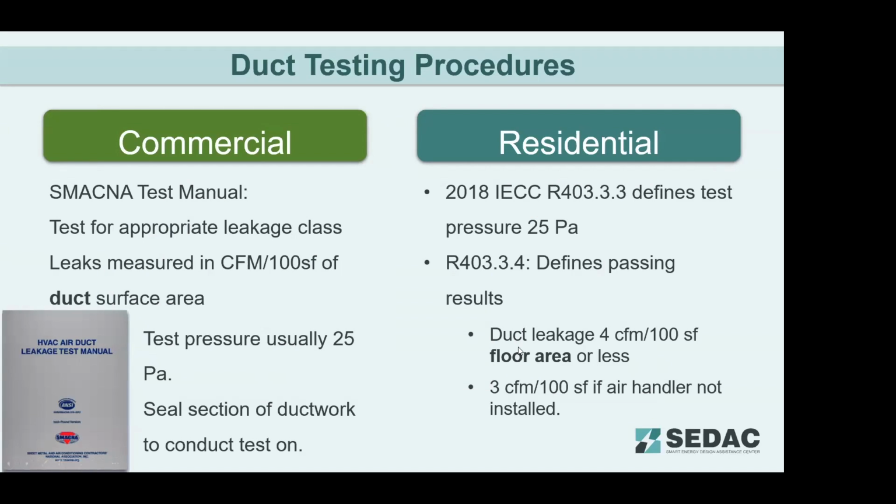So duct testing procedures, as Sean mentioned earlier, for commercial, reference the SMACNA test manual. Check your appropriate leakage class. Leaks are measured in CFM per 100 square foot of duct surface area, usually at 25 pascals. And you seal a section of ductwork to test on. On the residential side, 2018 IECC defines your test pressure at 25 pascals.